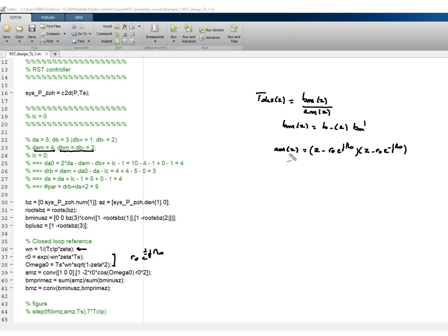We need a fourth order polynomial, so what we'll do is put two fast poles. So we'll use z minus 0, so that's the fastest pole that you can have, squared, right? So this one here is z squared minus 2 r0 cosine omega 0 z plus r0 squared, right? So this one you have over here, and this part over here, z squared, you have over here.